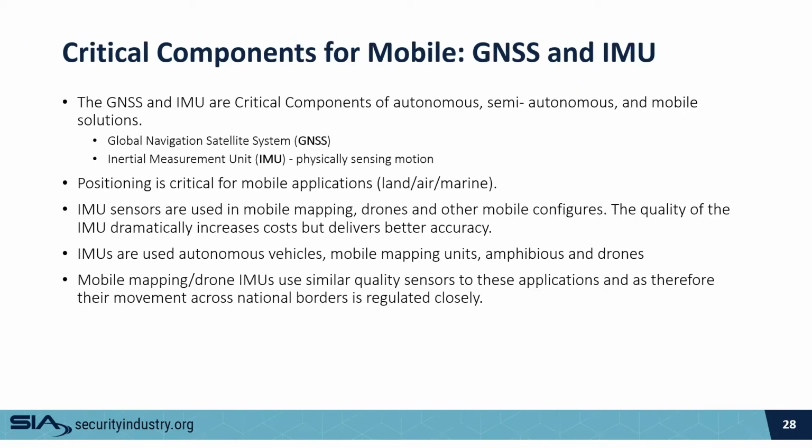So what are the critical components for mobile capture? There are two things we should know about, because the quality and the complexity of the setup can be part of the deliverable: working with a GNSS and an IMU. The global navigation satellite system, or a base station communicating with a satellite, documents our position as we change, and is going to be critical for drone mapping and sometimes SLAM. The quality of that dictates the actual measurability and quality of the data.